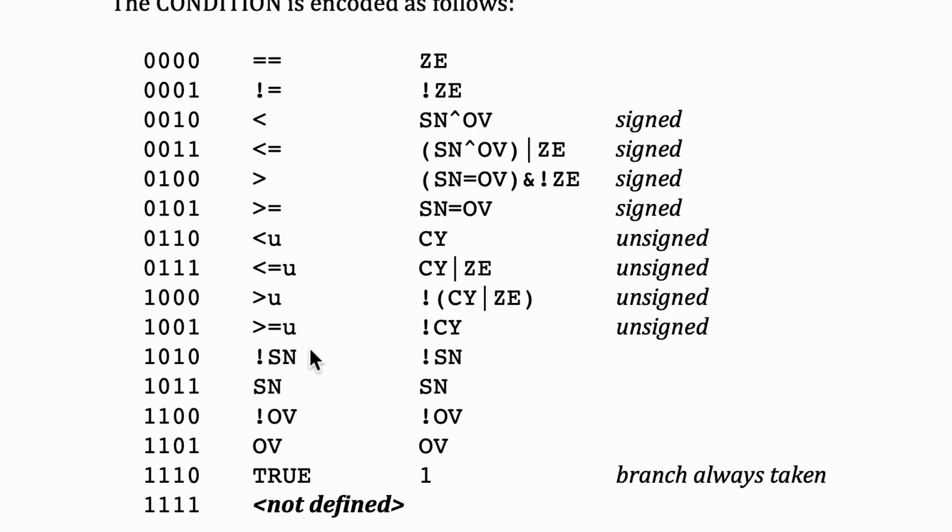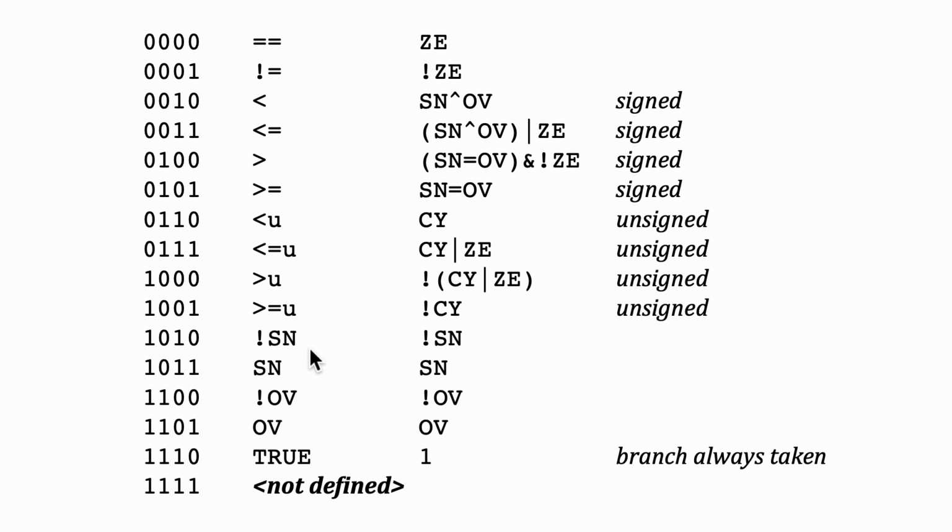The ALU instructions and the compare instruction will set the condition codes so we can do a conditional branch after one of those instructions. For example, if we compare A and B, we can then follow that with a conditional branch that will test, for example, whether they are equal, which simply tests the value of the 0 condition flag.